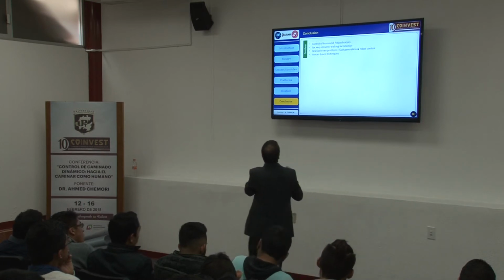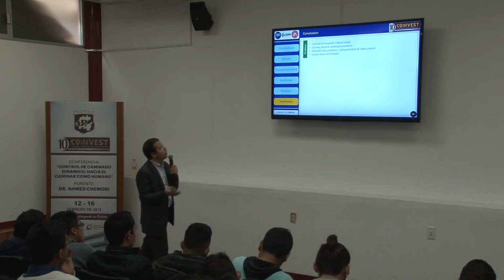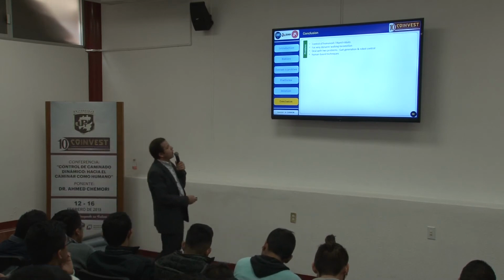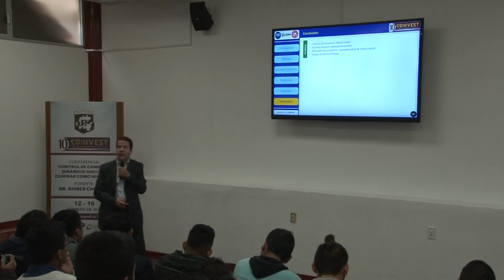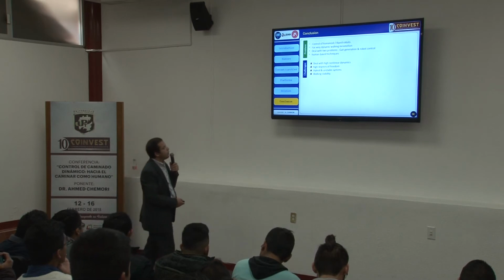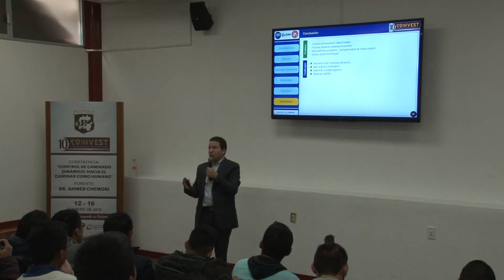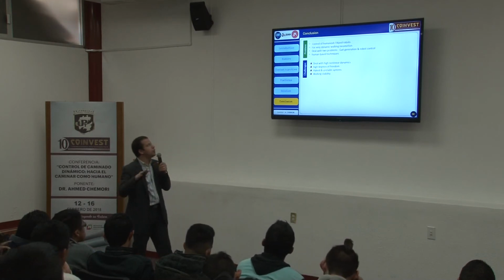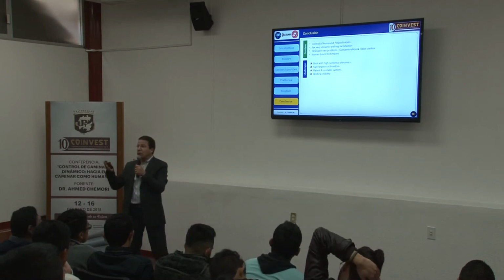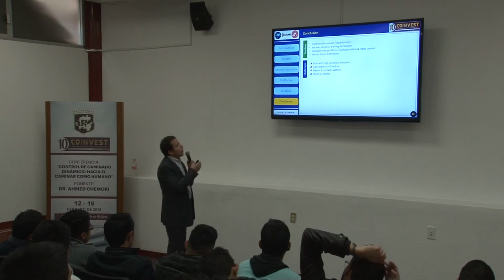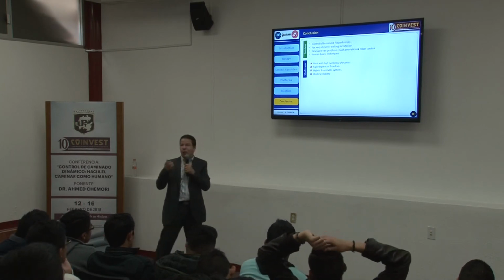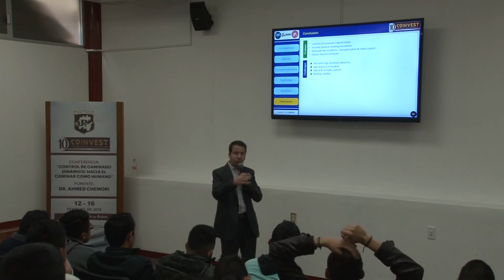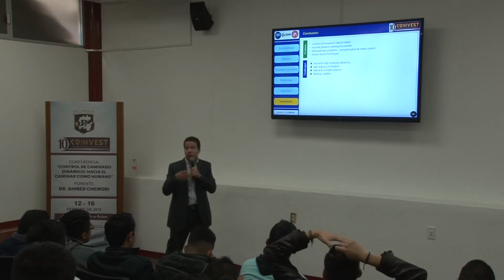We have to deal with some problems like gait generation and robot control. So we have trajectory generation and control, and we have tried to propose some human-based control techniques. To resolve this problem, you have to deal with challenges like the highly nonlinear dynamics, the high number of degrees of freedom, and the hybrid and unstable dynamics of the robot. Hybrid because of single support, double support, and so on, and unstable because it's very unstable.